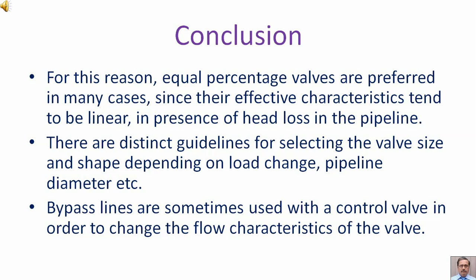There are distinct guidelines for selecting the valve size and shape depending on load change, pipeline diameter, etc. Bypass lines are also sometimes used with the control valve in order to change the flow characteristics of the valve.